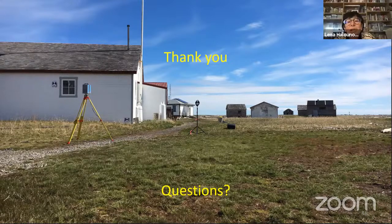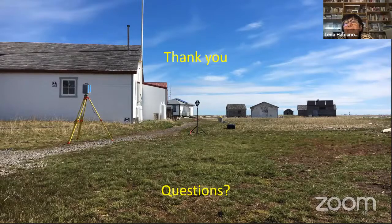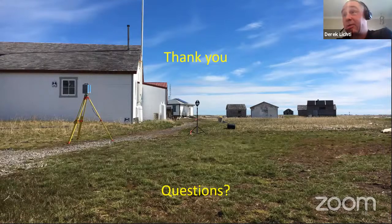I mean, atmospheric conditions, like fog, cause the atmosphere to become somewhat opaque, so you can't measure through it. And he meant also temperature. Temperature? Yeah, there are two aspects to temperature. We haven't looked specifically at the interior temperature of the instrument, but certainly atmospheric conditions will impact the accuracy of the range measurements. But in terrestrial laser scanning, distances are typically close, except maybe in mine site environments. I think it's really a matter of applying the relevant correction equations. If you can observe temperature and pressure, then you could in principle correct the observations to account for these effects.